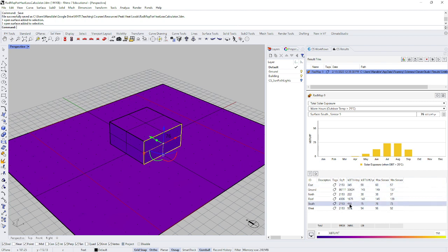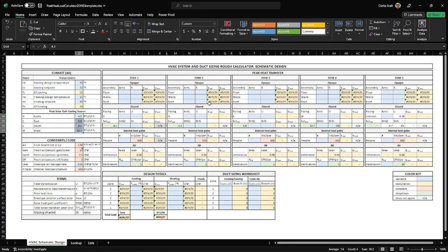I said, okay, 440 divided by 2.153 is going to get me kBTU per square foot per day, and then I divided that by 24 to get per hour, and then I came up with a number that I put into my spreadsheet. That was the 8.5, and then I did that for all of these faces. That's how I got those numbers. They should be somewhat accurate. So I picked the peak time that there's sun hitting, the peak month, and then I calculated an hourly peak.